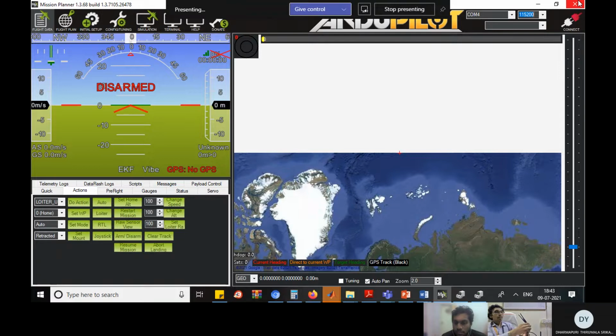If you have two antennas, you can go with the 90-degree phase for achieving a good pattern. Okay, so that depends how you are arranging the antennas. Or you can go with the Yagi antenna, the patch antenna, or the helical antenna, depends. So what type of antenna you are expecting for achieving long range, based on that you can decide.